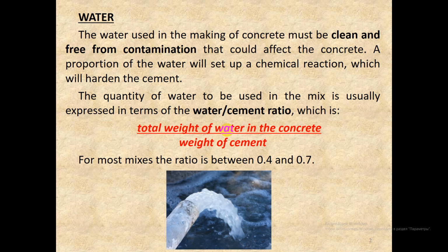But it's important to note that organic impurities in the water can cause retardation of the mix, and water must be free from chlorides, as this can cause steel in the mix to corrode. Acids and sulfates in the mix water can have detrimental influences, but this only occurs in the long term.